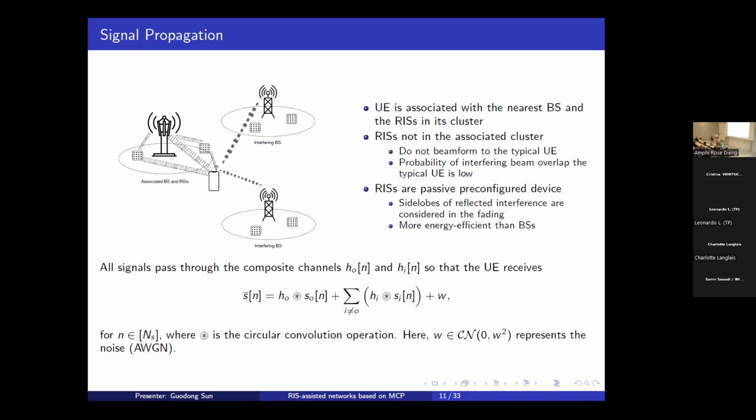So it's a time dispersive channel. We employ OFDM technology to mitigate this time dispersiveness or frequency selectiveness. So we send a string of signal over the OFDM block, then that time-domain signal is convolved with the channel. Then we need to analyze the overall channel gain of this OFDM symbol.